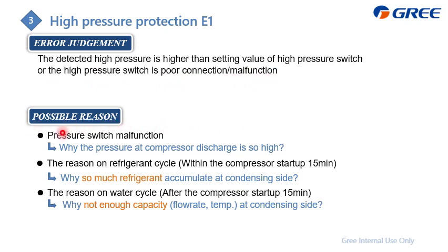So for the possible reason, first of all is to check whether the pressure is really so high or not. And you can also compare with your detected pressure gauge or check the pressure switch. And then we divide the reason into the refrigerant cycle and the water cycle.